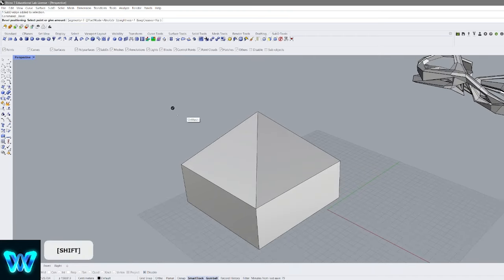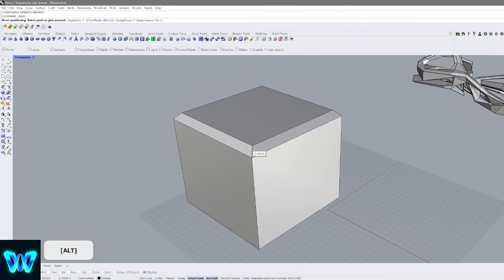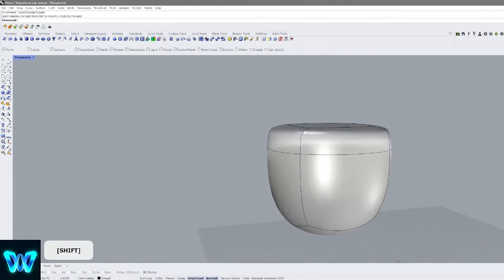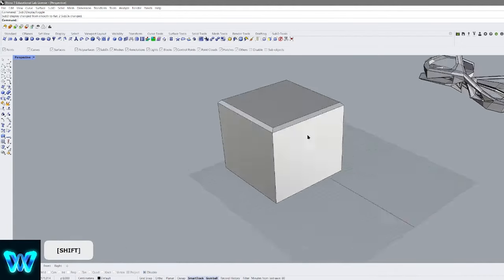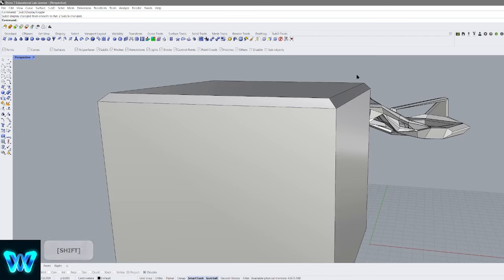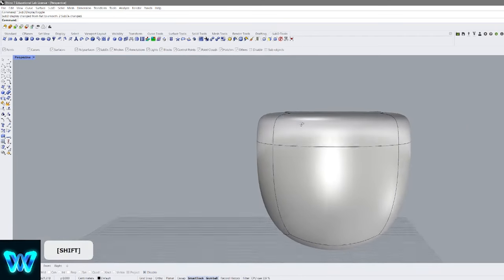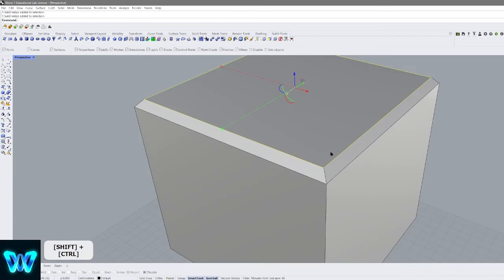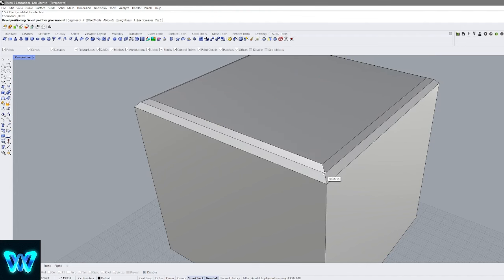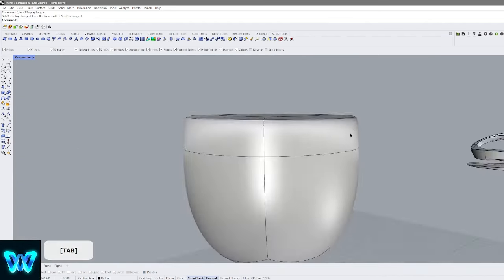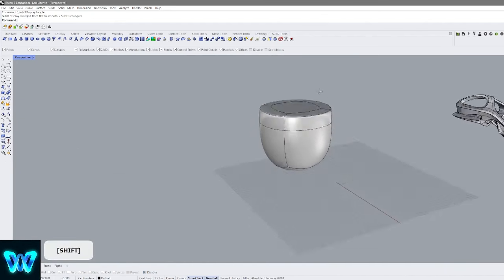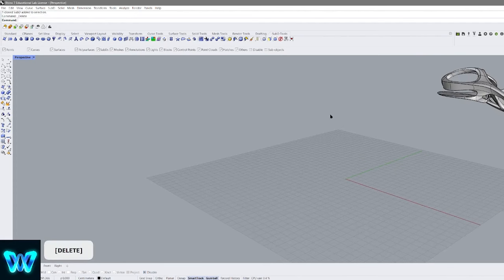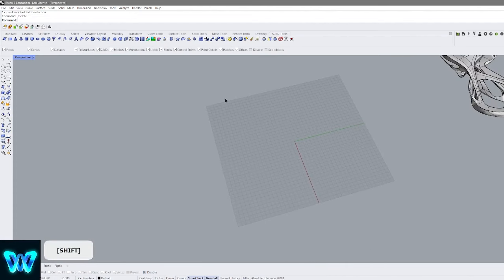Let's see. You will see that a lot more clearly. So you see how everything just gets cornered up. So that's how it works in SubD. In the polygonal mode, you will see more curvature because now you add a bevel. But in the non-polygonal mode, you will see less curvature. It starts to edge it more, right? So if I bevel this again too, we'll do it even further. It's more sharp, you see? It's a really good tool to create sharpness in your designs without having to crease it, because sometimes you want things that are more sharp but not creased, because creased is literally the most sharp it can be.